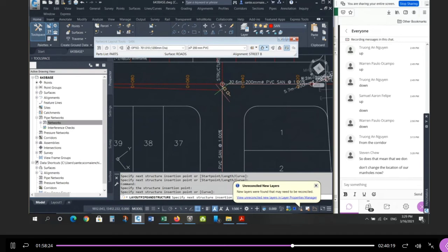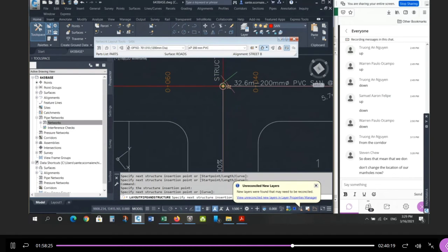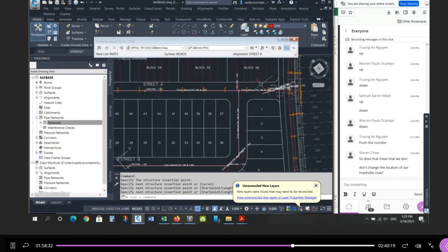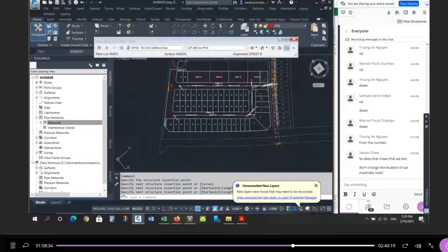This piece here. Okay, so when I snap here, it should only have one. It didn't create another structure. Okay, and now the system is digitized. To change the maintenance hole numbers, you need to change the structure name. The structure name. Don't change the labels, right?